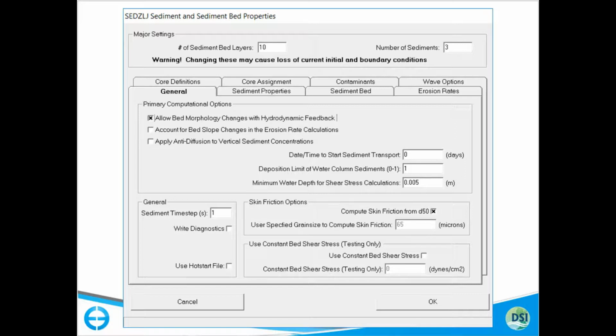You get the shock to the system and the hydrodynamics when you turn on the model and things start eroding and doing crazy stuff, because it's just the shock of the initial condition. So this gives you the ability, and we've added this to the original sediment transport model also, so now it's for both, to basically start up a run, let it run for a couple of days, let things stabilize in the hydrodynamics, and then turn on sediment transport.